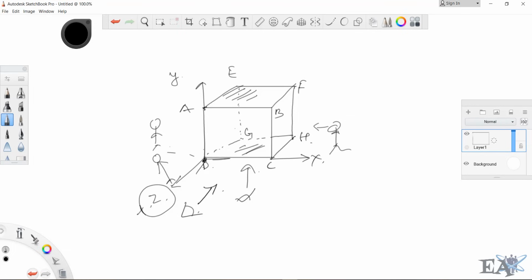We have drawn our beam like this. We have not drawn, so we'll be drawing. So right now the beam that we see is in the isometric form, that we see the entire 3D view, isometric view, or the entire 3D view of our beam. So to just see the beam in our plane, we have to see from the positive Z axis, we have to see from here so that we can see this entire beam in a plane.